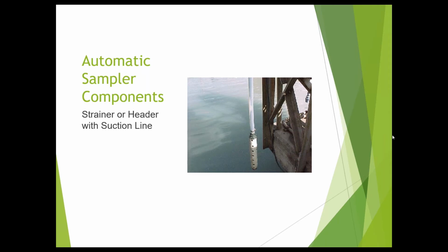So you're taking an estimate of what you expect the flow to be, and you're applying that to what your current program is. And that's one of the advantages of taking the sample, taking 24 or however many individual samples, and then flow proportioning them after. Because instead of trying to predict what you have or what's coming in, you are now looking at what actually went by.